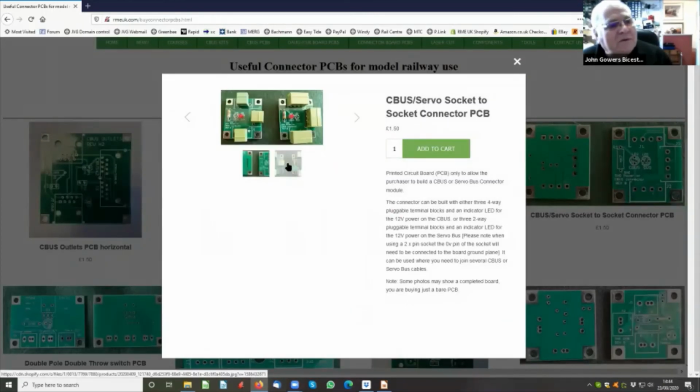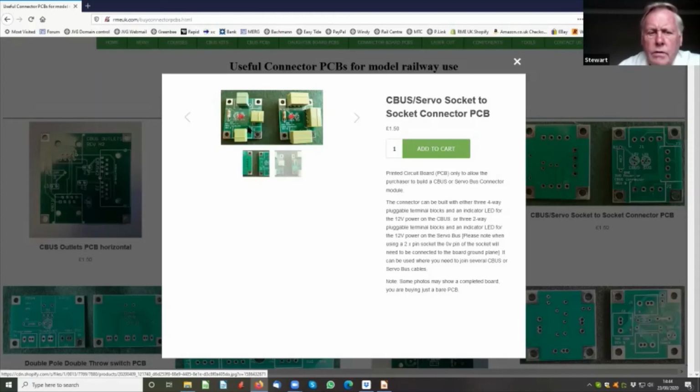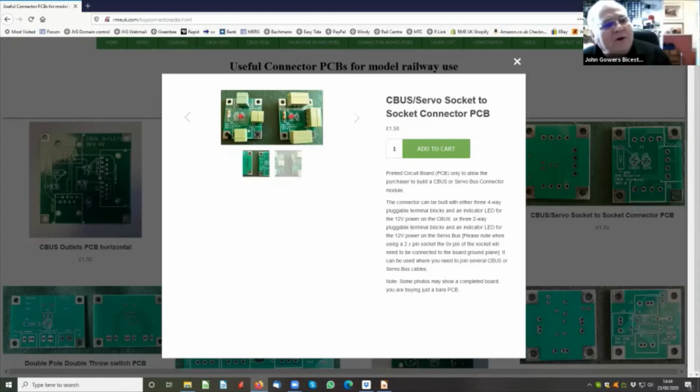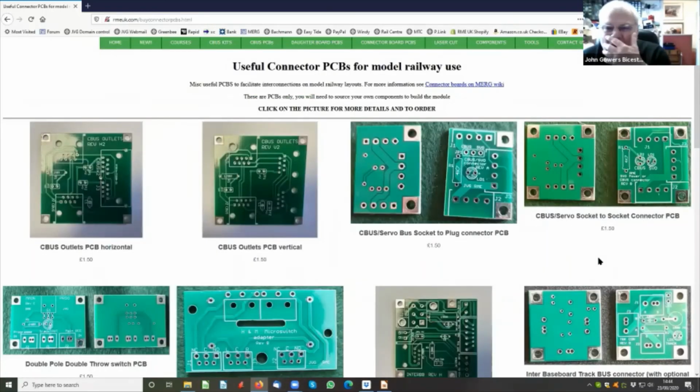You can see there, you can use it for two poles as well. I tend to use pluggables a lot, only because I've not had good experience with screw terminals, especially when you're trying to unplug and plug in, do something, and plug it back in. It always seems to be a nightmare. So I use pluggables. There's a downside, because every connection you make is a potential area for a slight fault or a loss. But yeah, so there we go.